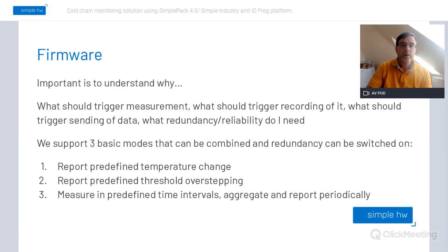That was the hardware part, and now we come to firmware, because we think that, especially with Sigfox, you need to have not only good radio performance, but you also need to have smart devices because of the limitations in the payload size and the limitation of the battery life. So very often it is important to understand why you actually want to measure the temperature, and what should trigger the measurement, what should trigger recording of the measurement, what should trigger sending of the data, what redundancy and reliability you are looking for.